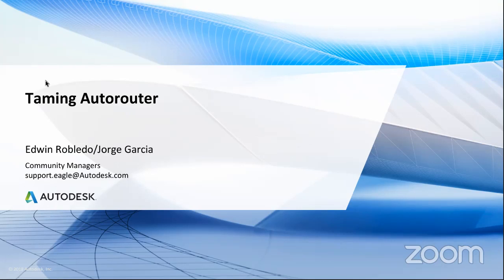Autorouter is a great tool if you use it correctly, but you should really primarily be working manually when you're converting your connections that came from the schematic over to your board. You should always consider using the manual routing features, because there's no way you're going to get an Autorouter to give you the same results. I know it's a lot more work. Now, if you need to do a quick spin and there's nothing all that critical on the board, let's say it's all digital, for example, then there are instances in which using the Autorouter you may be able to pull it off. But when it comes to final products, we strongly recommend that you always use manual routing, which we've covered.